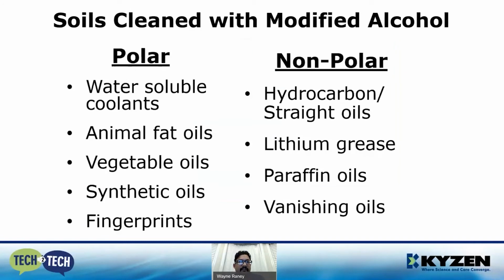Here's a list of soils that are cleaned from substrates using modified alcohol. Again, modified alcohol's cousin hydrocarbon has a tendency to only clean the nonpolar, or the materials listed on the right. But modified alcohol will clean polar as well as nonpolar soils. So everything from greases and oils to water-soluble coolants and synthetic oils.